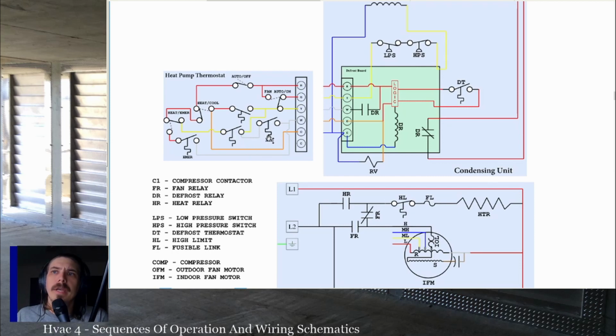Heat will come on at the outdoor unit after a set amount of time or deviance from set point. Then the auxiliary heat will come on, and both will stay on until the thermostat is satisfied. So basically, you have essentially 2 extra thermostats inside the thermostat, 2 extra temperature switches, and the extra selector to switch between heat and emergency heat.